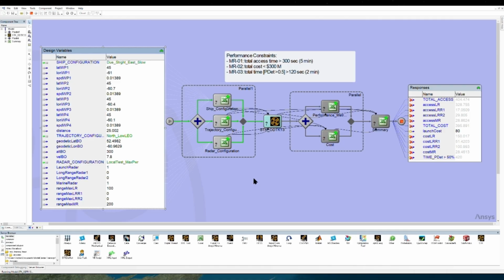By varying these inputs, we can automatically test how different mission configurations affect radar performance. The STK scenario outputs several datasets. This includes access logs for each radar facility, ship distance and speed over time, and figure of merit instances where the detection probability exceeds 50%.